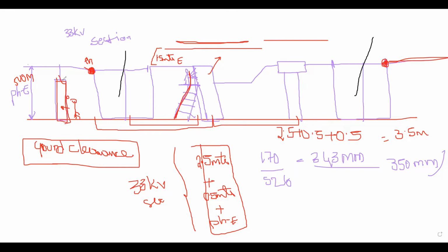So I have to place these insulators such that they are not within hand reach of a person. In a simple way, I have to ensure that any person working in this area cannot touch or damage the insulators accidentally.